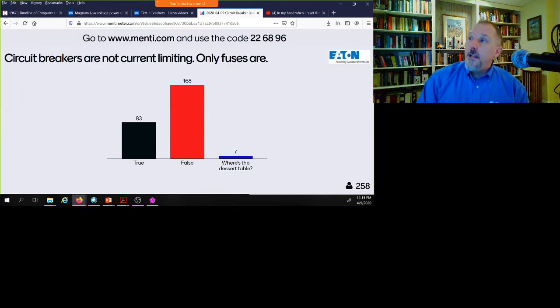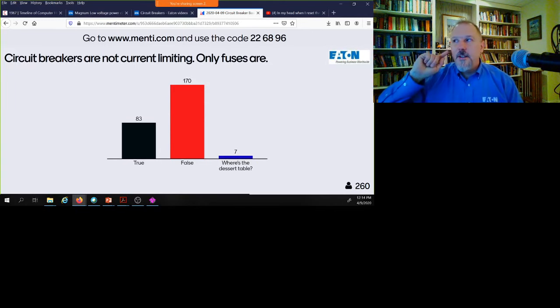Circuit breakers are not current limiting, only fuses are. 83 said true, 168 said false, and 7 are looking for the dessert table. That's fine. You 7, keep on looking, but watch this video because the right answer to this is false. There are current limiting circuit breakers.